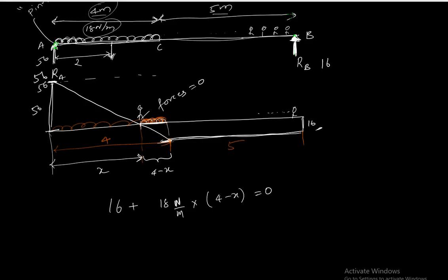Okay, and we're saying the force here is 0. Okay, so to recap, to find this distance x, to find where this point is, we say, okay, let this distance be x away from this end, right? And then we do the same thing as we were doing for calculating the shear force diagram, right? So we stand here and we're moving backwards. So when we're moving backwards, we keep seeing only the 16 Newton force, so that we have here.